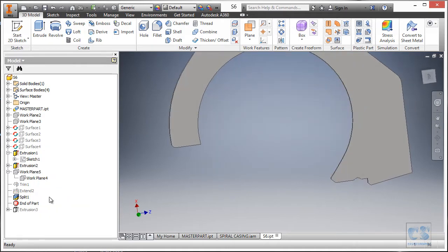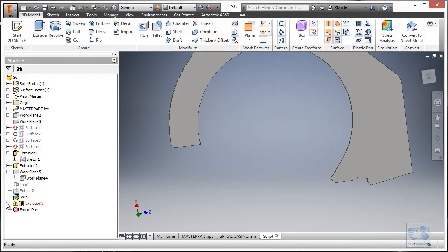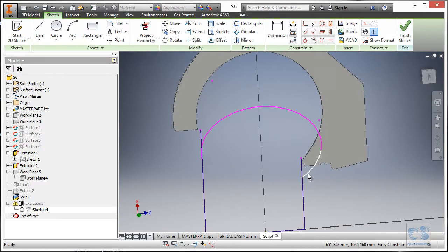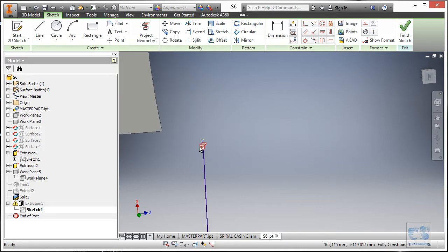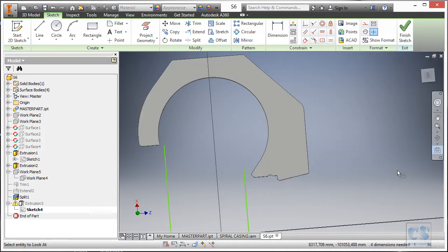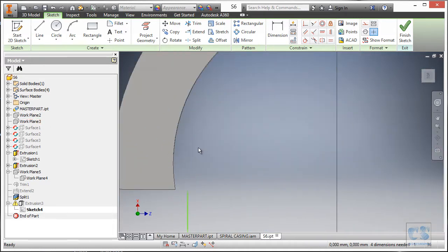And now we will finish the part by cleaning up the face. So back to the extrusion, and we will redefine this sketch again. We will remove this, all the magenta looking things. So this endpoint, this constraint first, then get this out of the way. At this end we have the constraint again, and let's look normal to the working plane. So I am sure that I will select what I need to select.